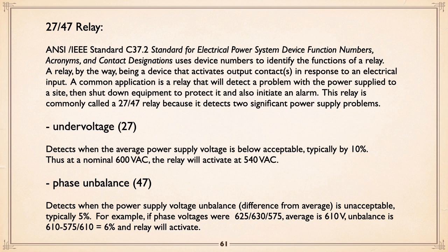Now, 27/47 relay. We're getting a little advanced here, but so be it. There's an IEEE standard for device functions, and basically these are relays that serve certain functions. And what a 27/47 relay does, number one, it's designed to protect for undervoltage.